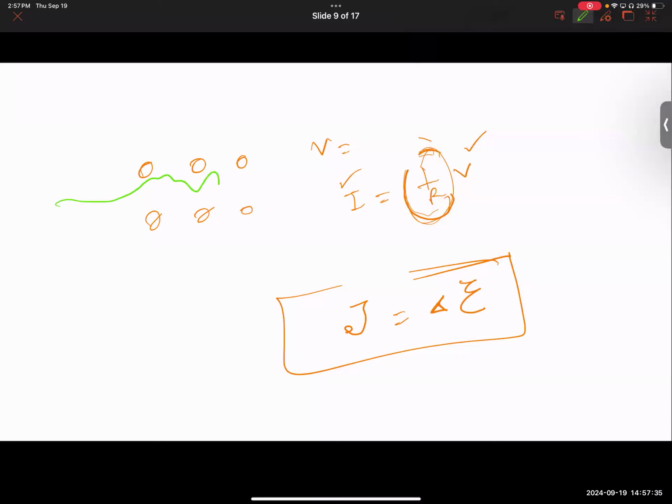So the electron will interact. The higher the speed is, the more interaction, the more scattering will occur, okay? There is a certain separation of atoms in a specific crystal, and the maximum velocity that you can reach is determined by the separation of the atoms in a crystal.